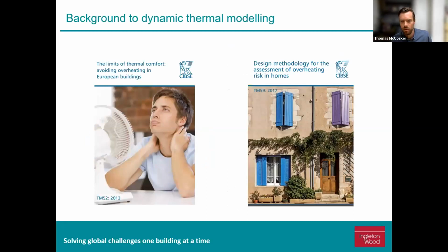As Jason mentioned, the simple method for compliance with Part L is a much more cost-effective way to do this because, as he said, it's not a simple method, it's just a simpler method. If compliance for a simple method cannot be achieved, a dynamic thermal model must be run. Although, as Jason was saying before, it might be better to change the design and get that simple method to pass because this dynamic thermal modeling is expensive and very detailed.